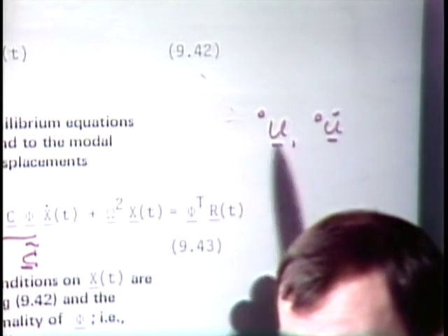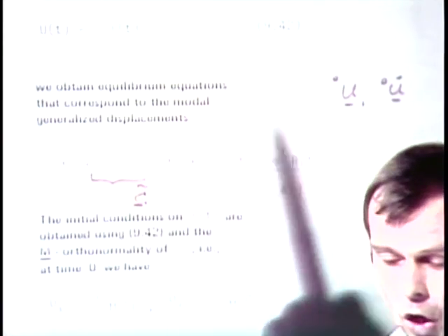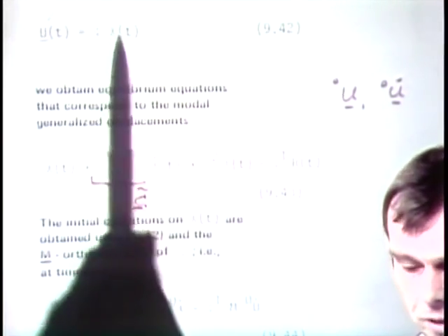These, of course, are the initial conditions that are used in the direct integration solution of the governing dynamic equilibrium equations. If we are now performing the solution of this set of equations, we will have to transform these initial conditions to initial conditions on the generalized displacements. And that is achieved via these relations here. Let us see how we derive these.